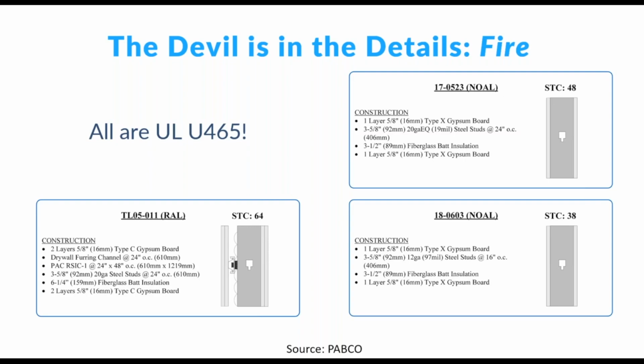All right, so now let's look at fire, but still in terms of acoustical performance. Something I've seen sometimes show up in architectural drawings is a wall that needs to be acoustically rated, say a demising wall between two apartments, right? It will be specified in the architectural drawings and the assembly drawings, but just based off of a UL design, and not necessarily a ton of construction details directed at the acoustical performance. And these might be design build projects, where the architect has a smaller budget, or there's delegated design for steel stud walls and things like that.